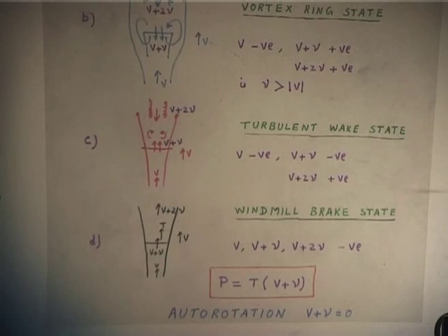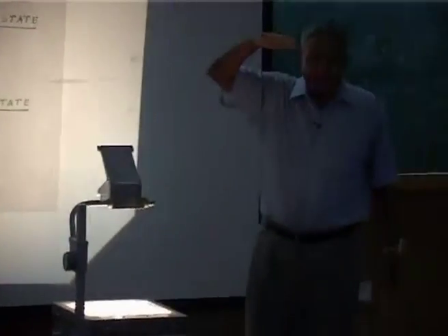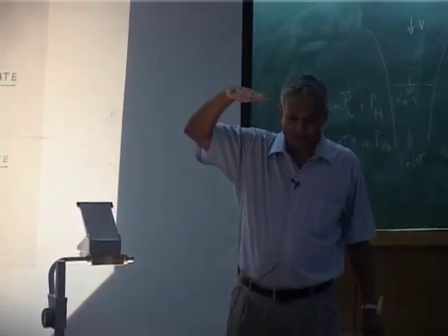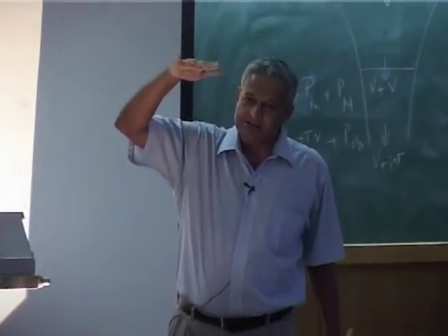In case of engine failure, because you are rotating, engine fails, because of its inertia it will still rotate, but then the drag force is acting, you are not supplying any power. Then what will happen? If you do not do anything, if the descent is not there, then rotor will come to a stop. But what you do is you immediately start descending.